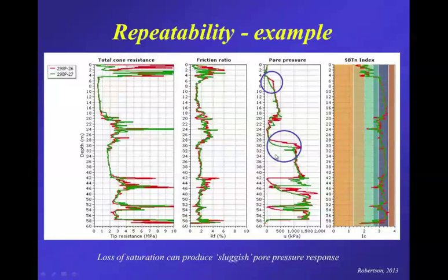That's one of the challenges of pore pressure: it may start off initially saturated, but you could in fact lose saturation, then gain it, and then lose it again, gain it and lose it again. So interpretation of pore pressure data in mixed soil conditions can be quite complex.